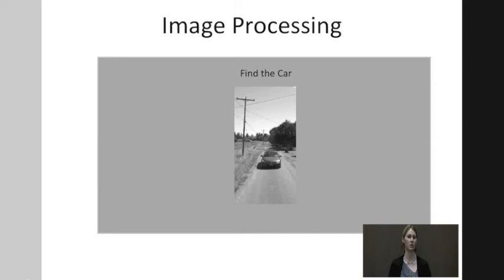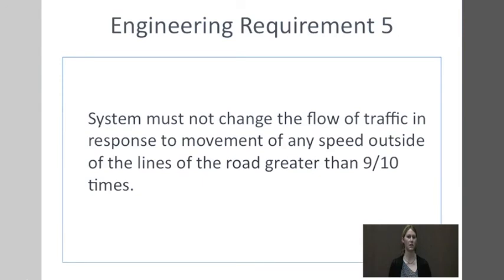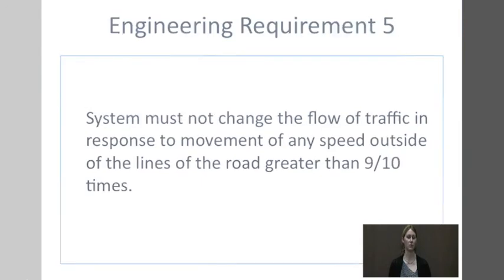Next, the 2 images are exclusively ORed together, pixel by pixel. The resulting image, as seen here, turns white wherever there is a difference in pixel value indicating movement. Notice that the movement from the bushes and trees in the background is also picked up by this algorithm. Most of this noise is filtered out by the filter stage, and the rest is small enough that it can be ignored when searching the image for the car. The system must filter out this noise so that it does not accidentally trigger the light.